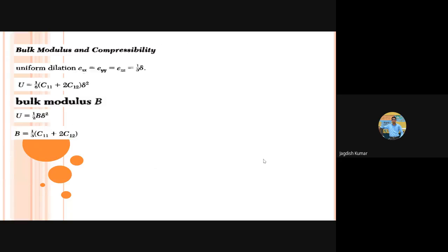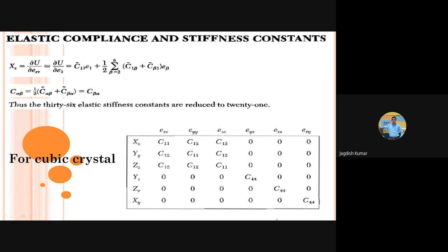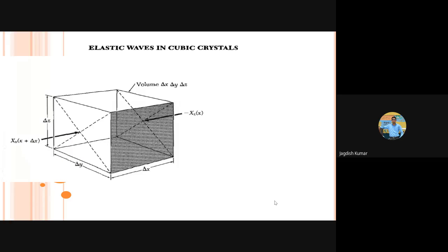It means we are fixing these constants according to this rule, so you have only 3 independent values of Cij's, and these values are related to the microscopic nature. They come from the structure of the crystal and what kind of symmetry that structure has microscopically.